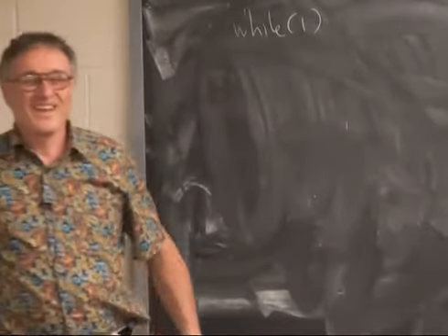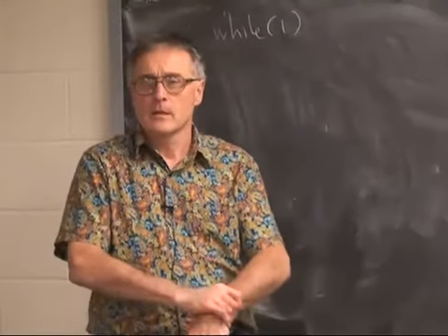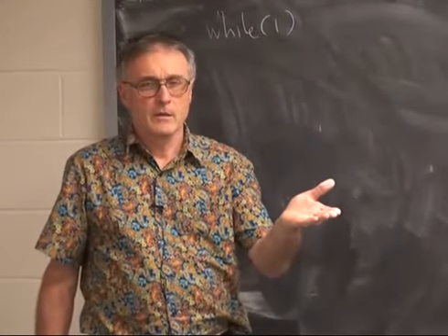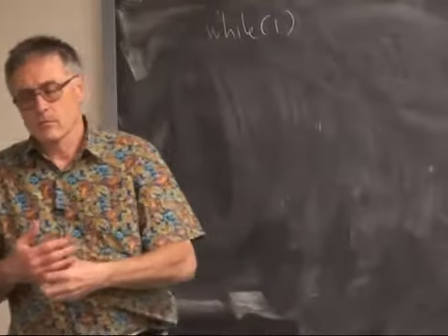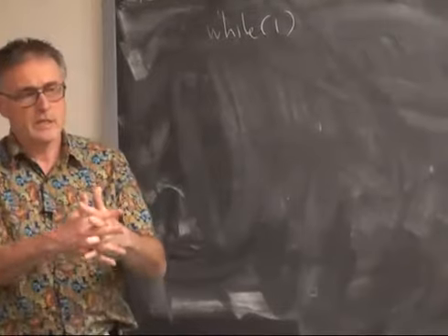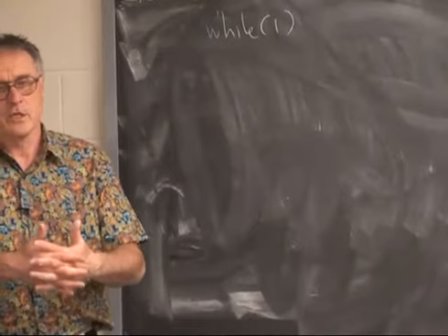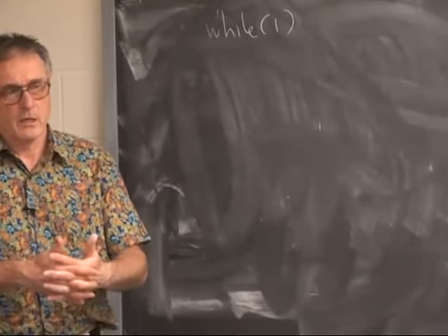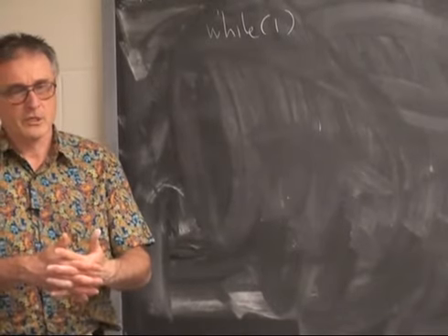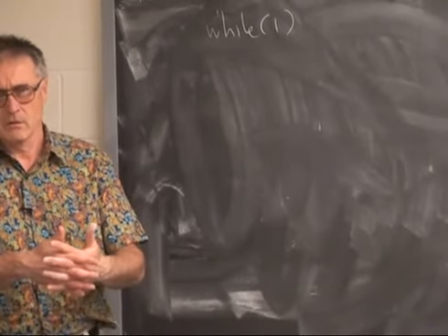Do you have a question you want to ask about generate blocks? Okay, so a generate generates hardware. It is not an iterative structure. You cannot ever instantiate a module in an always block, because that implies that you're going to instantiate hardware on every cycle.